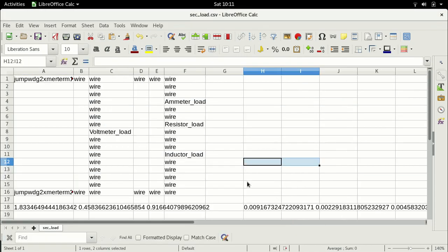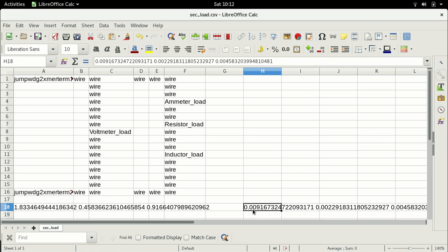So if we compare, we see that in the first case with the 50 Hz transformer, the self-inductance of winding 1 is 1.833 Henry. This is with a 50 Hz transformer. Now with a 10,000 Hz transformer, this is the value you get. Your self-inductance of winding 1 is now 0.009 Henry, which means it's 9 millihenry, right?